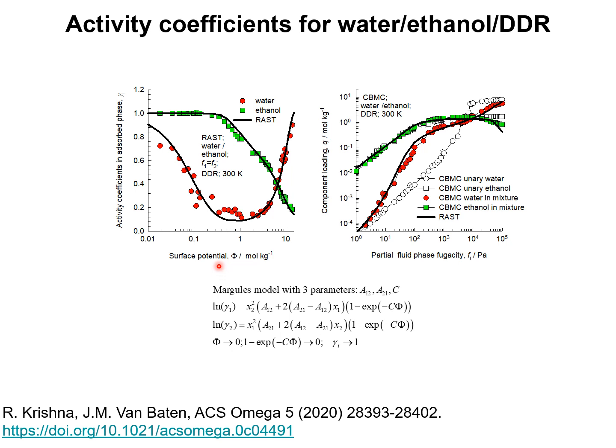Experimental data on mixture adsorption and activity coefficients are rather scarce and quite limited, and therefore the use of the RAST relies heavily on estimations of the activity coefficients based on CBMC data. But such data are not always available, and for many cases the CBMC simulations are not accurate enough because the force fields are not reliable enough for determination of mixture adsorption equilibrium.